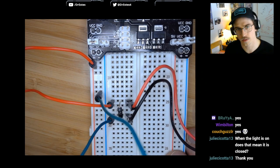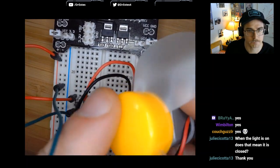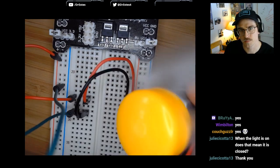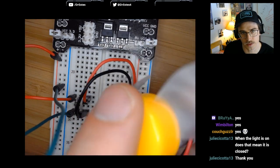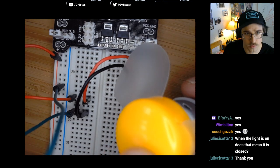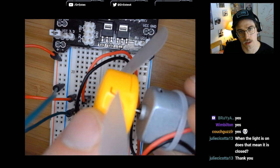This is a diode. The reason I have a diode here is when you turn on a motor, this acts like an inductor. And what I mean by that is there's a magnetic field that's generated in here. When you turn off the motor, that magnetic field needs to dissipate.